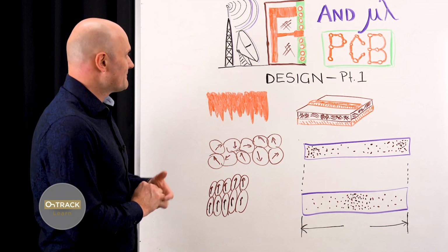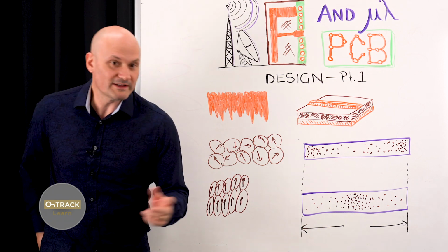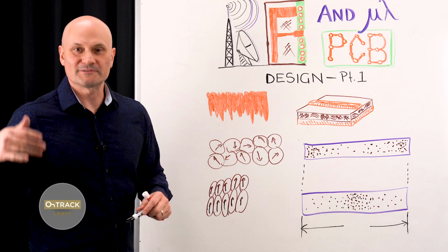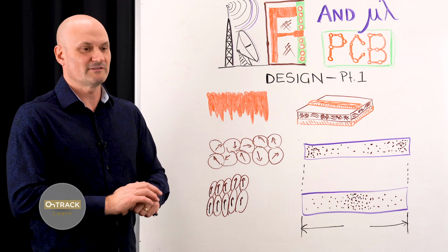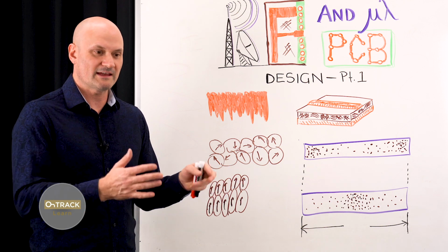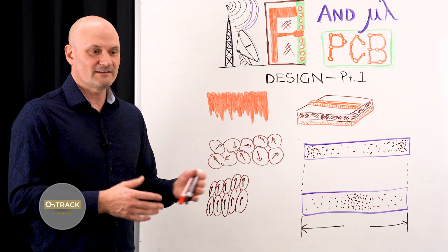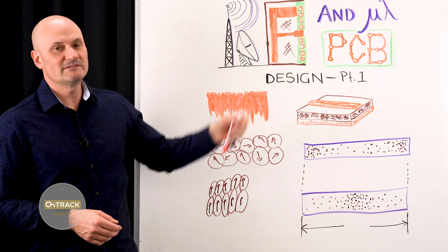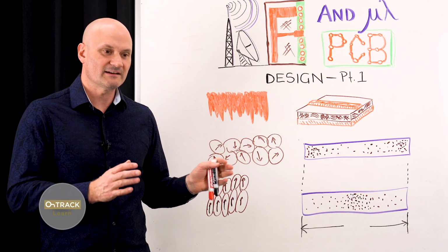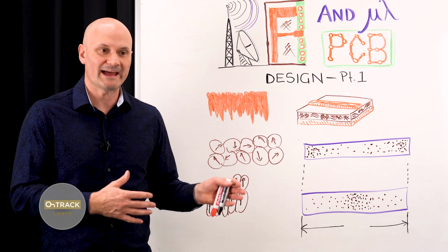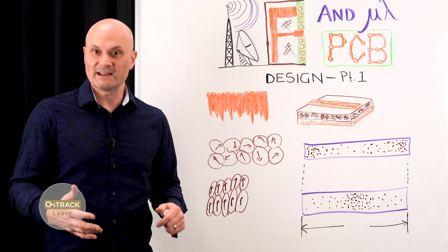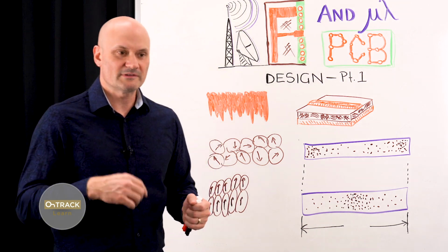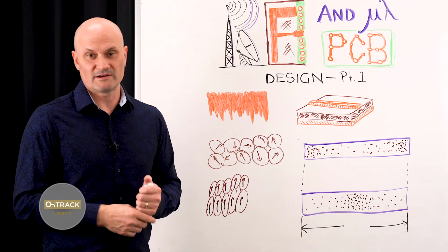First of all, let me actually say, what is RF? Really, RF, or radio frequency, is anything like 300 kilohertz or above, technically. And you can go on the FCC website, for example, or if you're in another country, there'll be a government website where they have information about laws that regulate the use of what we call the radio frequency spectrum. But really, as far as RF and PCB goes, we're talking about anything that's intentionally processing, amplifying or carrying analog signals from or to an antenna, at frequencies in the megahertz and above. Microwaves is when we get up around 1.5 gigahertz and above.